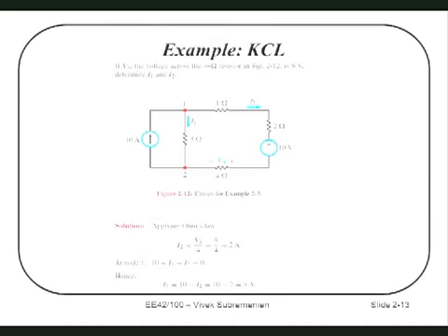Okay, tell me, what is the voltage across here? 24 volts. How do you know that? 3 ohms times 8 amps. So this is the answer. The reason the current goes in is because this source is stronger. And it essentially generates 24 volts. Well, 24 is more than 10. Voltages are all relative, so it's going to go in.